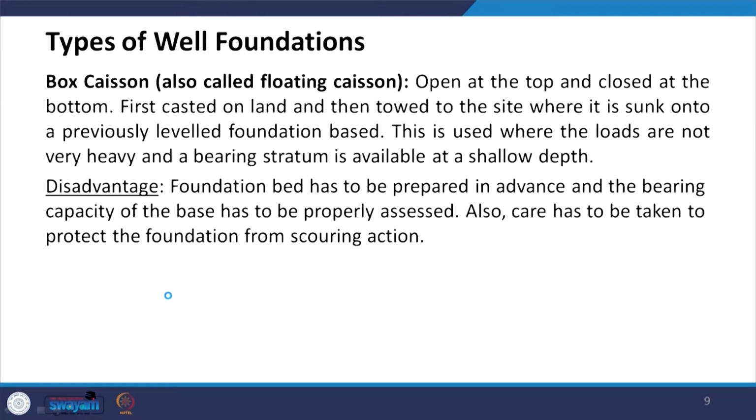Okay. The disadvantage written here again is that the foundation bed has to be prepared in advance and the bearing capacity of the base has to be properly assessed. Also, care has to be taken to protect the foundation from scouring action. So, this was the story about box caissons.